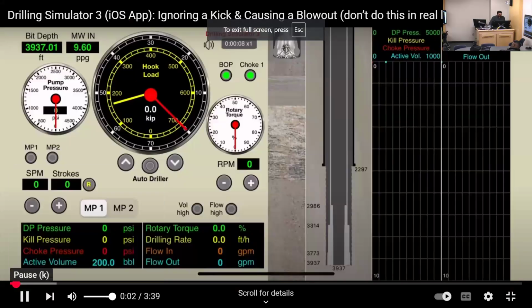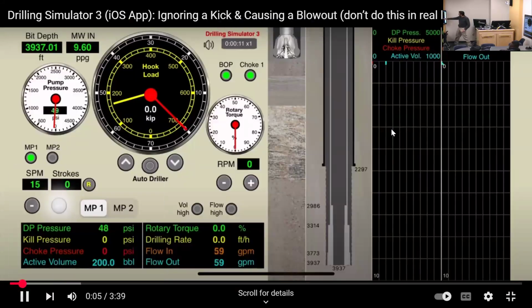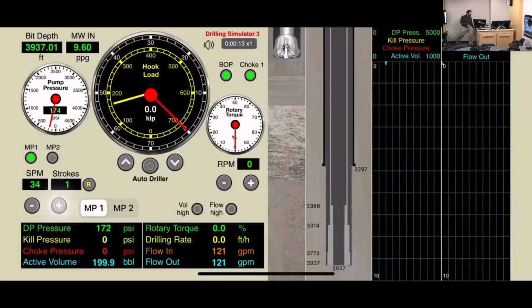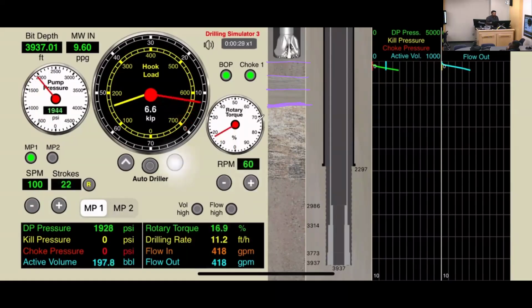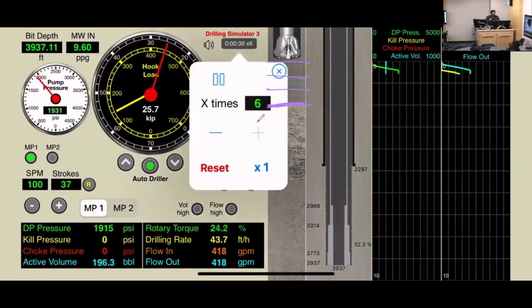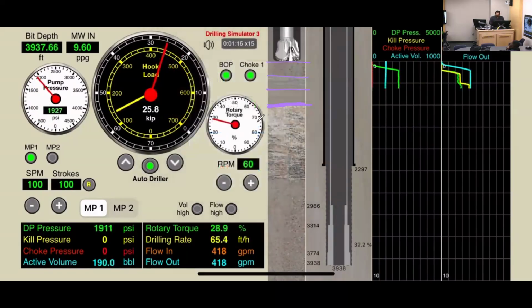Look at the screen here. As I'm drilling, the kick formation is here. You are going to get a kick after you pass that point. This is one formation, this is another formation, and you will see the ROP changing. Now I'm starting to drill with the same process I said earlier: circulate, rotate, add weight on the bit. Look at the yellow line, it's the ROP line. Once I pass this stage, it's going to change. It's going to go down, I think.